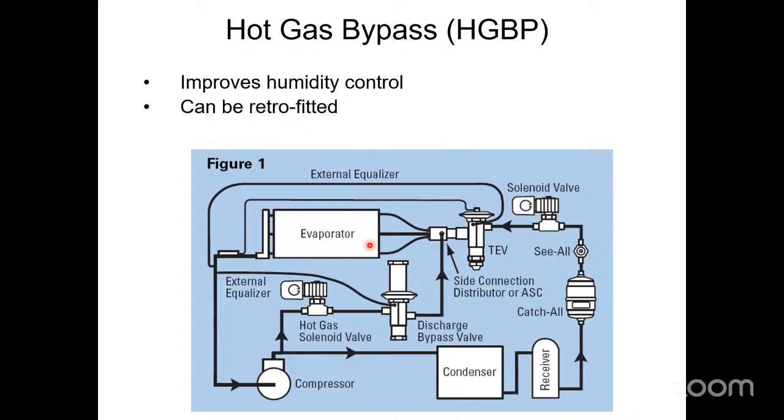But you really need more compressor stages. So you can shut off compressor three, you can shut off compressor two, and now compressor one is on by itself, but it's still too much. You're allowed to put hot gas bypass on that lead compressor as long as you're under certain percentage capacity limits of the whole system. You're allowed to utilize that. So it's kind of a way to cheat and get that fourth stage if you can't get it a better way.